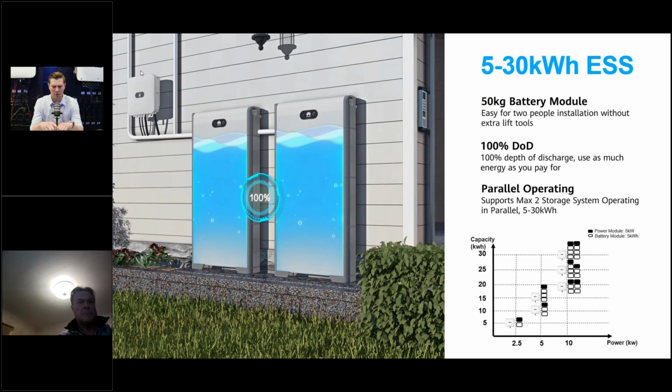This chart below shows how much power you can take from the system in different configurations. As you can see, the 5 kilowatt hours is applicable only when you have a 10 or 15 kilowatt hour system. If you have only 5 kilowatt hours, the output power is only 2.5. It's because we cannot discharge over the charging and discharging current limit of the battery.